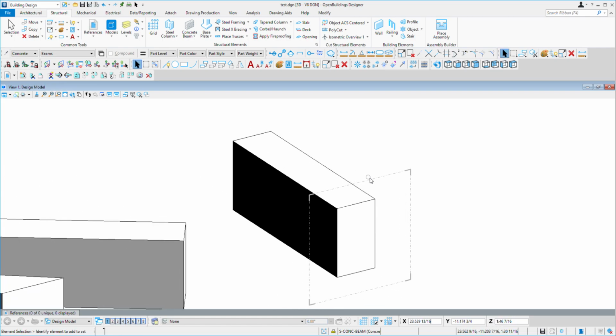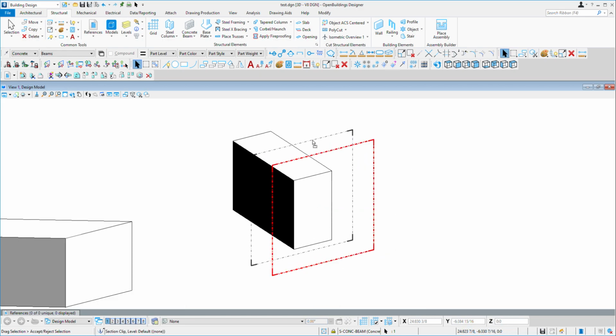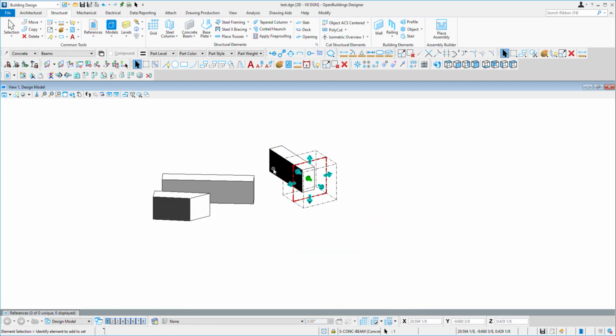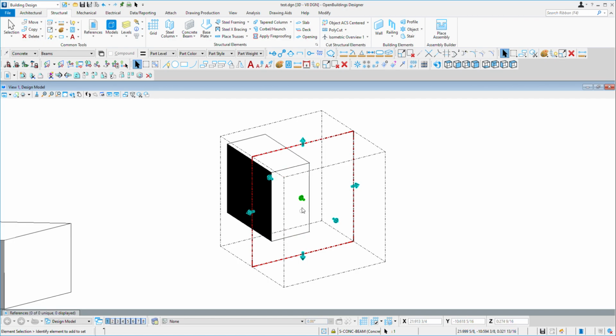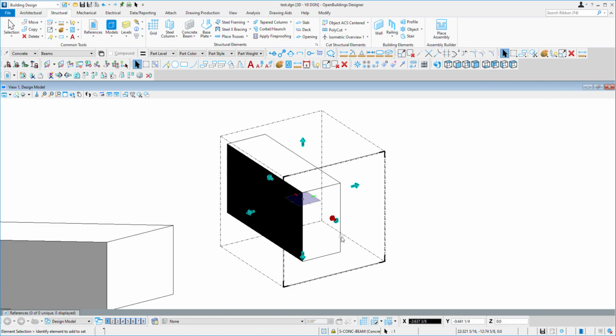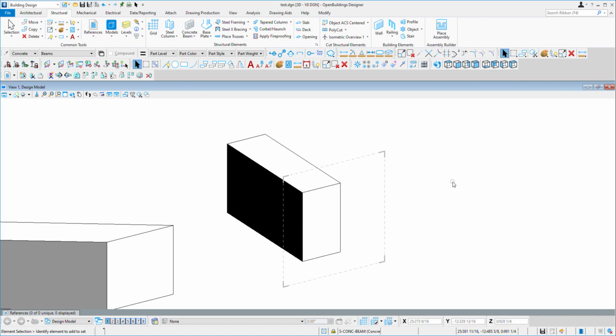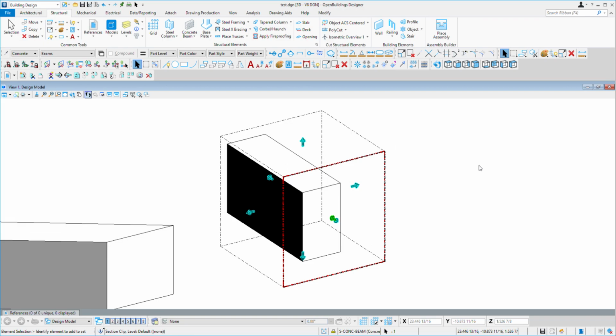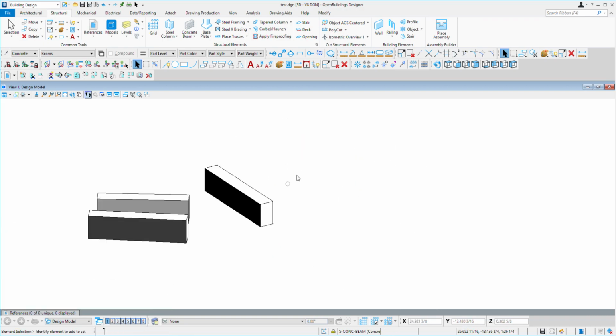And you can modify it also like this. Like we have several things, we have two beams, one beam here and one beam here. It gives you the facility to choose where you want to see, what you want to see, and where you want to cut that section. And this is also clip volume. Clip mask is also required when we make 2D drawings, and it is also for referencing. So I remove that clip boundary by deleting. So it is the normal view.